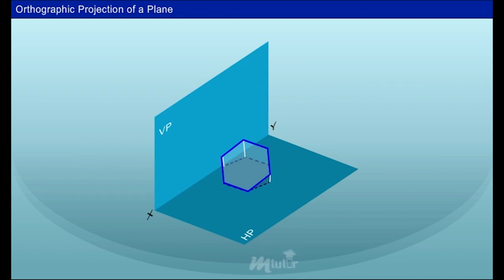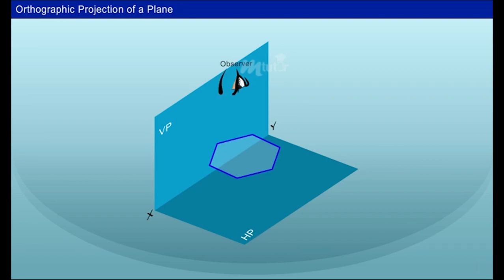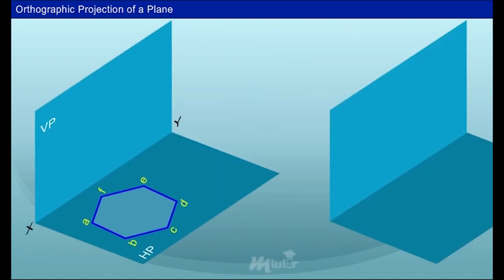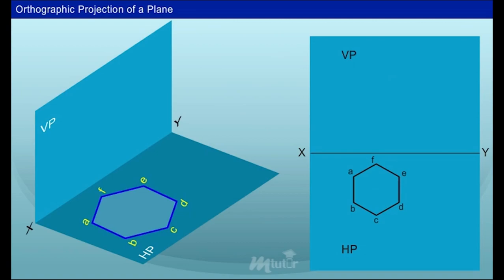With the help of its simple position, we can draw its inclined position to any plane. The first step is to obtain the true shape of the hexagon in its simple position. Since it is given that one of its edges rests on HP, that is, initially the plane lies on the HP, the top view gives the true shape. Also, it is given that one of the edges rests on HP and its surface is perpendicular to VP. The hexagon can be drawn as shown with the side 30 mm.